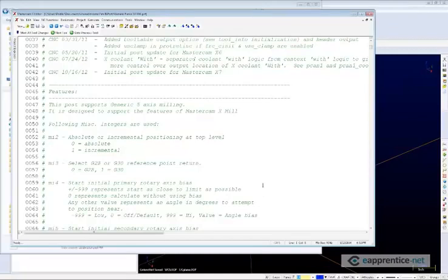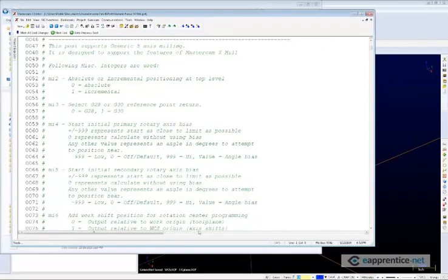So we're taking the generic Fanuc 5X mill post, we're going to configure it for a table-table, something like the Mazak Variaxis style of machine, and then we're going to do a head-head, something like a CMS router or a Cincinnati router, any of those 5-axis gantry style routers. We're not going to be going in and changing the entire output of the post for something like, say, a Siemens. We don't have time in the 3 days of the class to do that. But I think for anybody that is getting into 5-axis post processing, the class is really going to cover all of the basic stuff that you need to know in how to use this post.